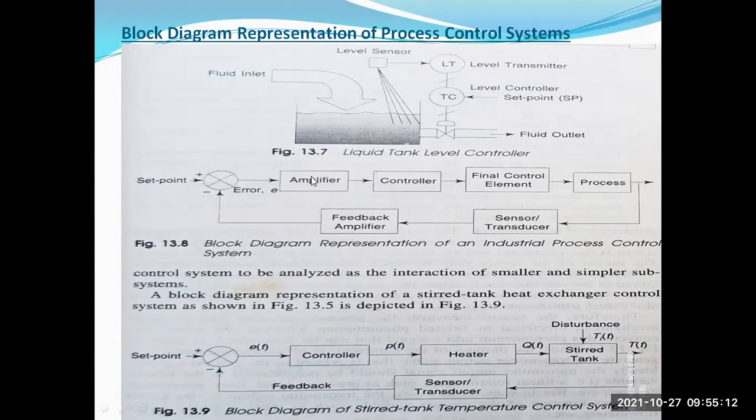One is the controller part, these are the controller sections. Another one is connected here: you can see this is the feedback loop or feedback element also. So please remember these things also. The set point or reference input is connected in two sections. One is the input to the controller part. The other is also connected to the feedback loop or feedback path. Clear? Is it clear?